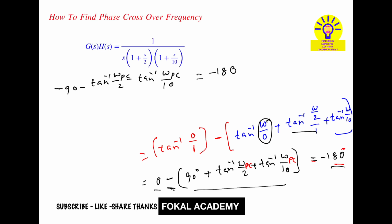Keep it as it is, without taking the minus common, so the minus signs will cancel. Now tan inverse of omega pc by 2 plus tan inverse of omega pc by 10 equals 180.